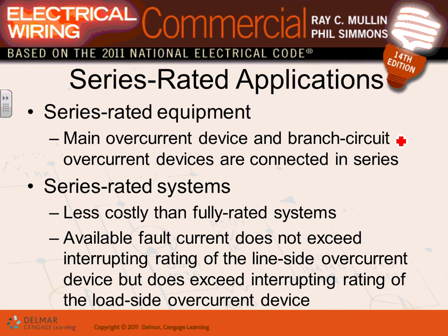You're going to be doing this one, guys, with me next time too. There's something called series rated. When we invited Todd Christensen, I don't know if you guys remember when he was here, he talked about series rated equipment. Series rated equipment is a cheap way of doing it, typically for receptacle panels and lighting panels, where you have two circuit breakers rated. One of them is rated for a higher interrupting rating. The second one is rated for a lower interrupting rating. They work together to handle the short circuit condition. So it's a great application for lighting and receptacle panels.